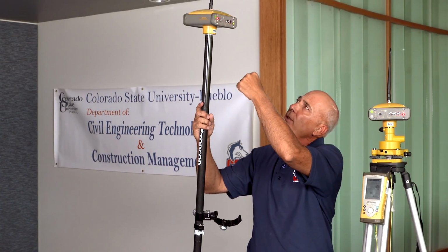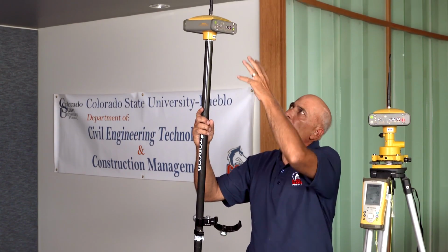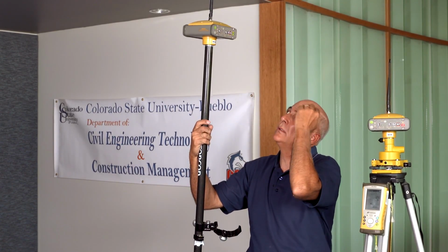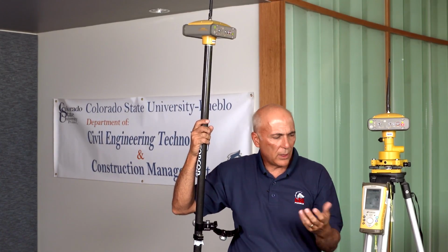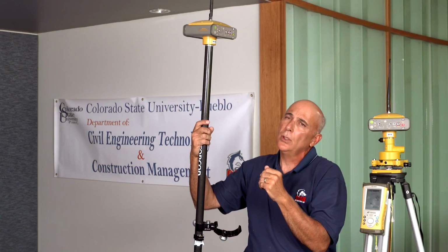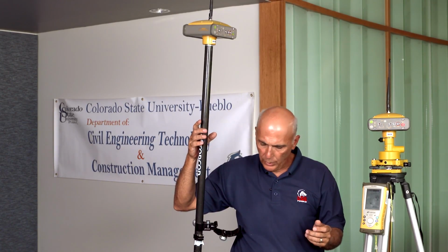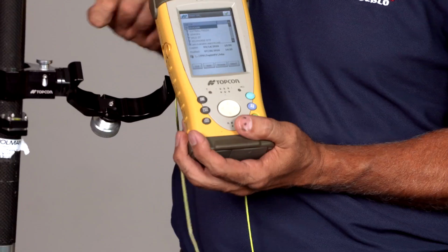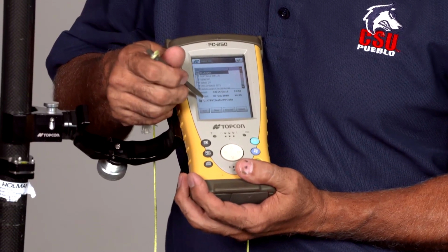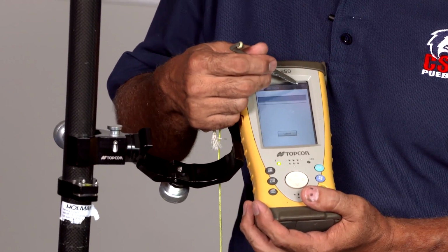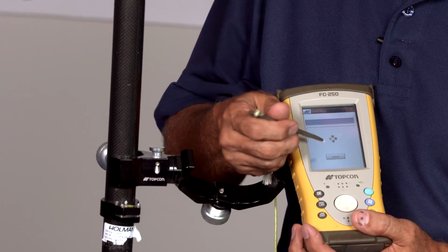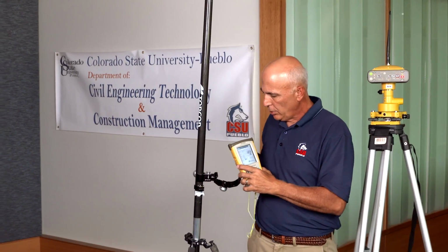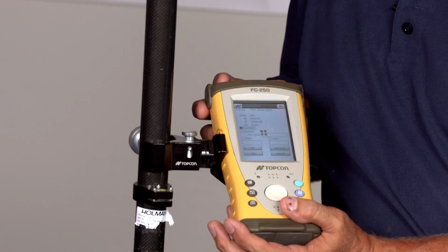So in the situation of the roving unit, we would turn it on, have our light sequence similar to that of the base unit, making sure that the sequence is in compliance with the manufacturer's specifications, and each of the lights indicating whether or not it's properly receiving satellite communication. The next thing we would do is take our data collector, the same data collector that we used when we set up the base unit. The difference now is that once we've set the base unit up, it's not necessary to keep communicating with the base unit because the base unit's signal is being sent to the roving unit. So now what we're concerned about is communicating with the roving unit.